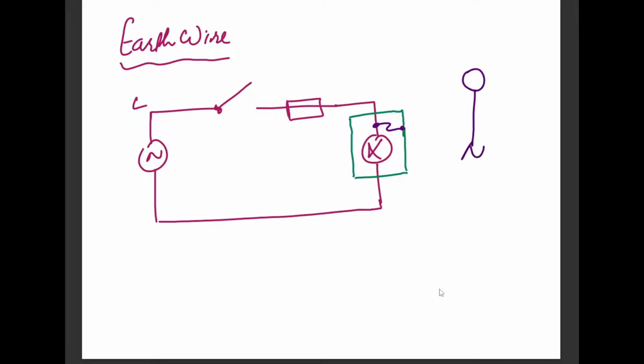So if the operator comes close to the appliance and touches the metal part of the object, you may have experienced this sometime in your life, that you get an electric shock from the metal part of the appliance. Why has that happened? Because internally the live wire has accidentally come in contact with the body of that metal appliance. This is why you will see that we are now shifting towards plastic bodies for most appliances where we can. The washing machines and all of them are having plastic bodies, because that adds another layer of safety, because plastic is a poor conductor of electricity.